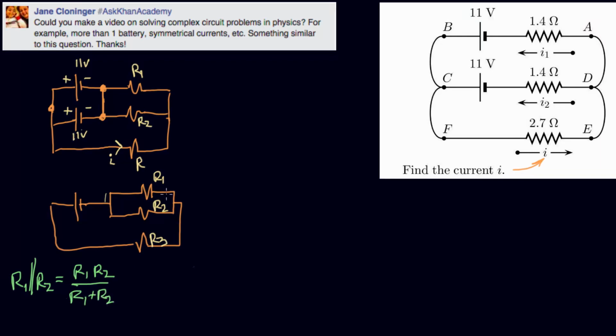If we look over here at our schematic, R1 and R2 are the same value. And that has a special property in parallel resistors. So it's actually R over 2R, because those resistors are the same. And you can see I can cancel that, and I can cancel that. Two parallel resistors, if the resistors are equal, is equal to half the resistance.